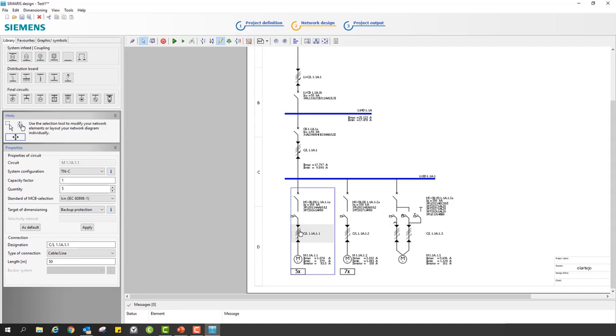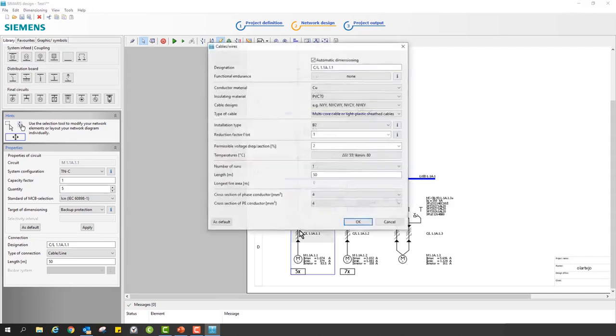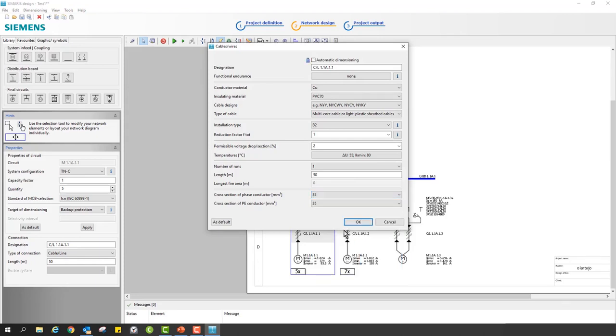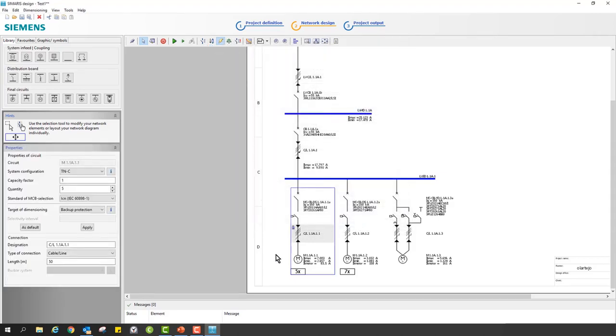But when you consult and ask your customer some questions about the distances and about where the control panel will be installed, you'll be able to crack out a lot of information and even tell him that he doesn't need a 50 kiloamp control panel, that he needs a 25 kiloamp or a 17 kiloamp. This will reduce his costs, your cost, and you will do a better design for what is actually needed.